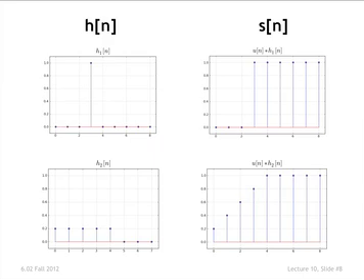A typical system might ring indefinitely, might respond indefinitely to a kick. All these examples are ones where the system has a transient and then settles down. And so what you expect to see in the step response is a transient and then it settles down. The difference is in the step response, it settles to another value. It doesn't come back down to 0.